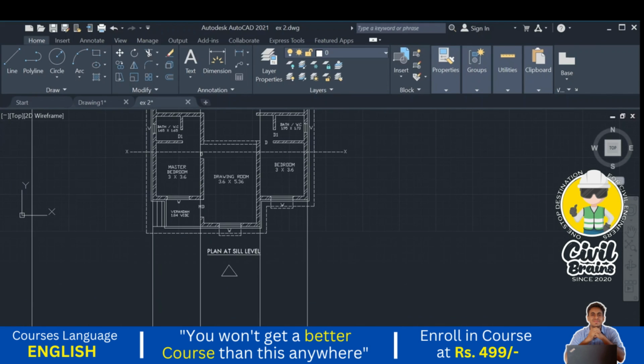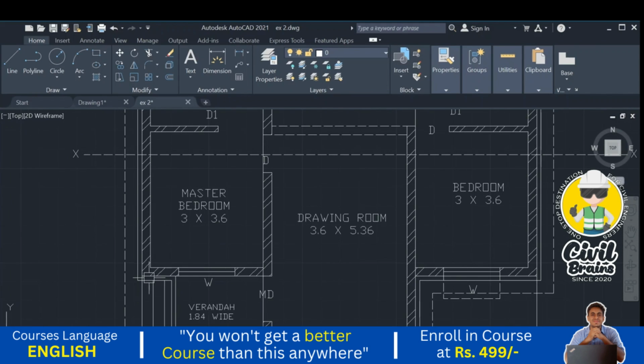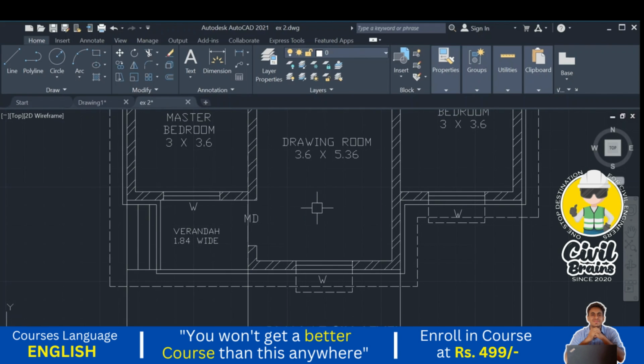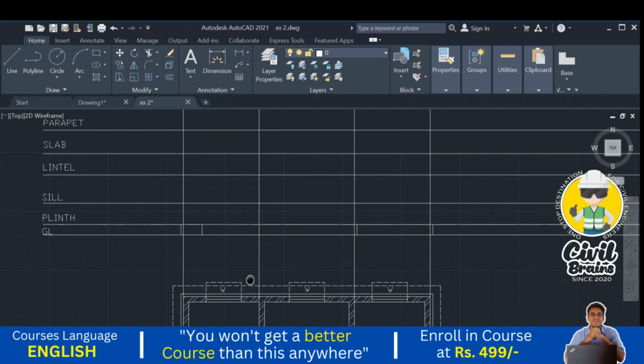So this wall from the plinth, up to which height will it go? From the plinth up to the bottom of the slab, the same wall will move. Above that, the parapet sometimes will change. Sometimes it is provided on the projection also, sometimes above the wall also, and the thickness of the wall also will change. But here from the plinth to the bottom of the slab there is no change in the thickness, it will go the same. So the same thing we need to do.